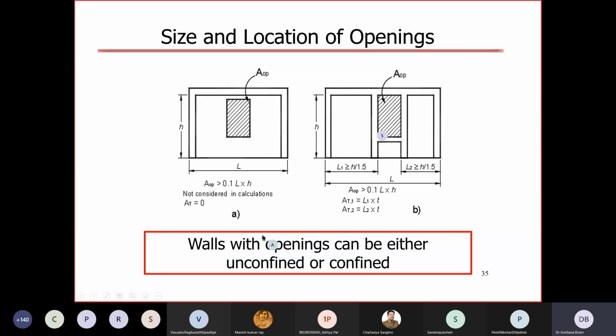That is one rule, and that is the only way. So in other words, look at this left and right confined masonry wall. These two walls are confined, and this one shown under A would be unconfined. What does it mean? The wall would exist, no question, but it would not contribute to resisting seismic forces. That is all. And the question could be whether we could provide some nominal reinforcement here, which is a good practice around vertical and also horizontal direction.